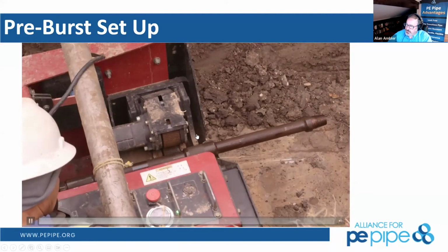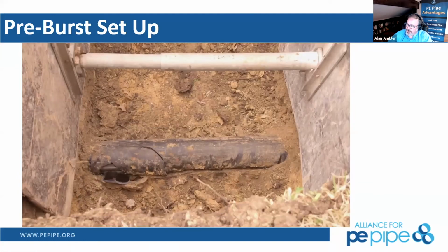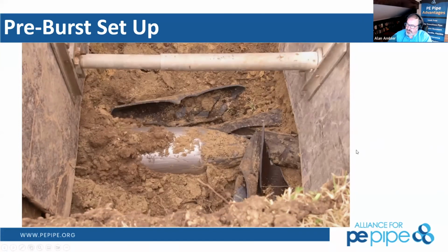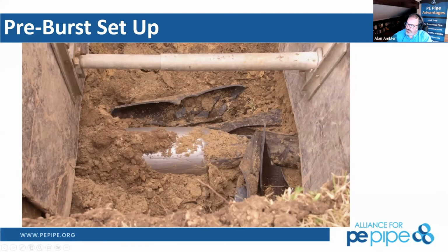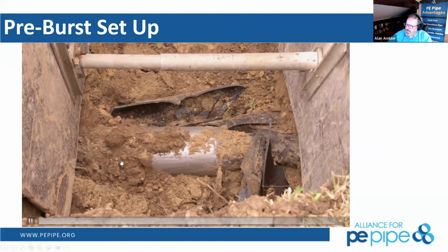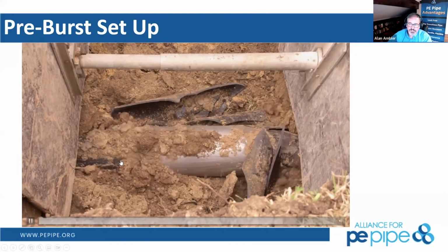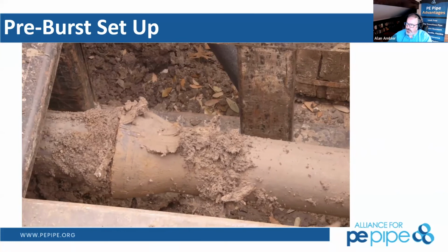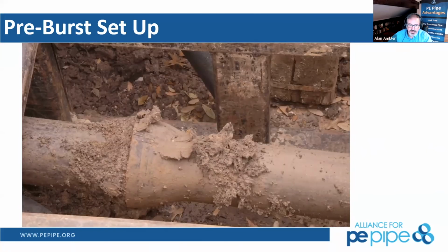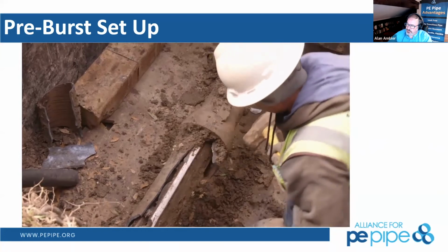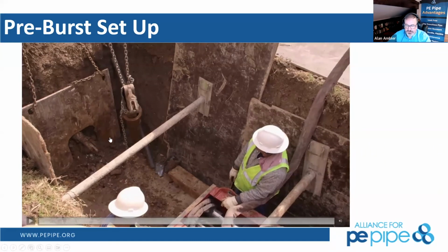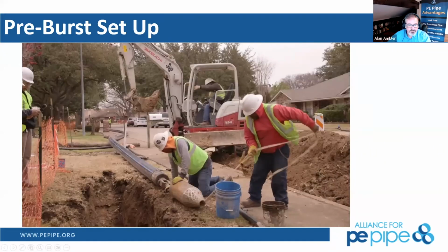Here you're seeing some drill string that's attached for the pipe bursting mechanism, and a unique way for the machinery to make sure that they're winding up that string. And again, just bursting cast iron. This is a video from No Dig Tech in Texas. John Newell does quite a bit of pipe bursting. The expander head, of course, doesn't care what it's pulling through. So if it didn't break the pipe in a situation like this, it'll pull it through the ground, and then the crew simply breaks it off of the pipe as they come.